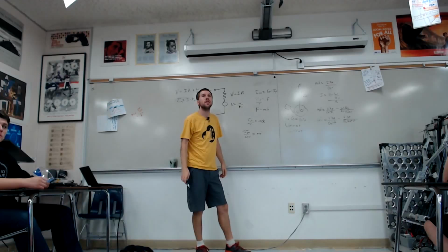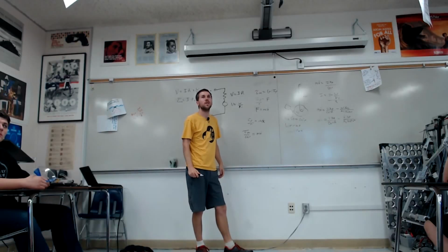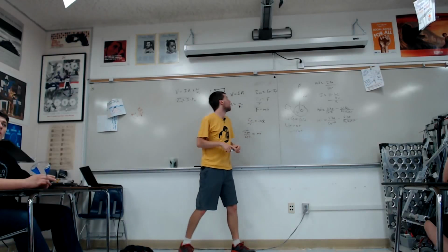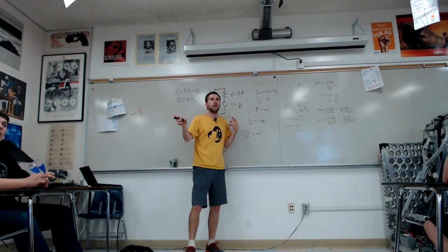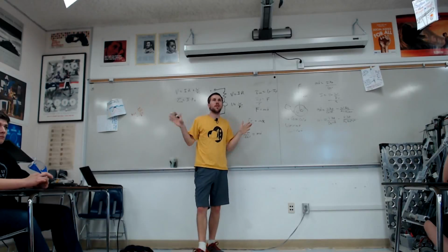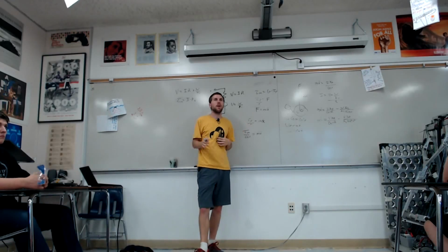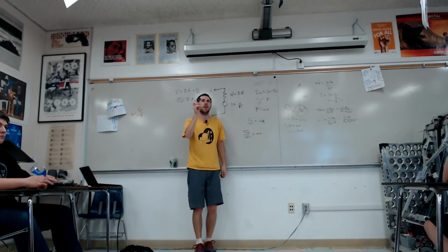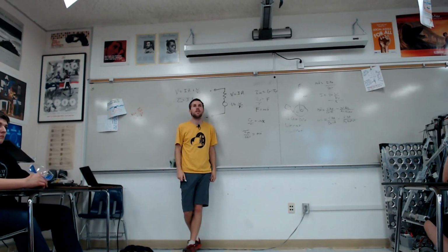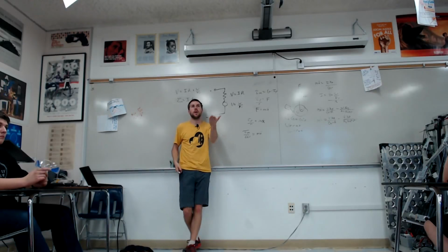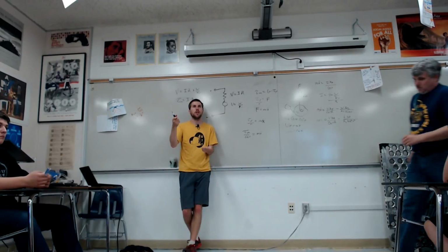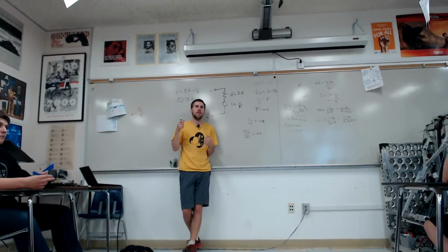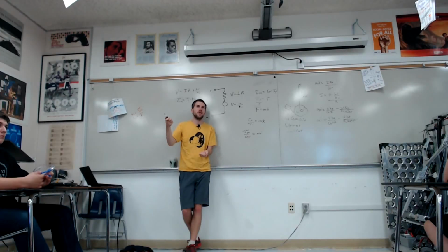Question: can you just repeat what the end thing you're trying to solve for was? So our physics is going to have an input and output. We want to get rid of all the things that aren't in that input or output list. So what is the input that you apply to your motor? Yeah, you apply electricity, which is voltage. It's really voltage and current, but on your motor controller you give it a duty cycle, which gives you a percentage of battery voltage.